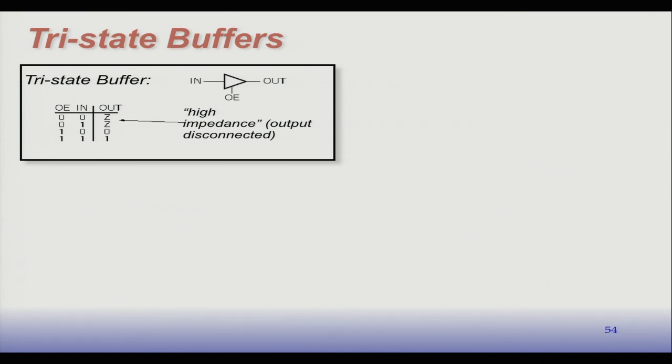And these are interesting circuits that kind of violate our principle of static CMOS in an interesting way. The symbol for this one, it's a non-inverting version. It looks like an inverter without a bubble on it, which sounds kind of silly. It has no logical function, but it has this electrical function. It has an extra input here called output enable. And here's the truth table.